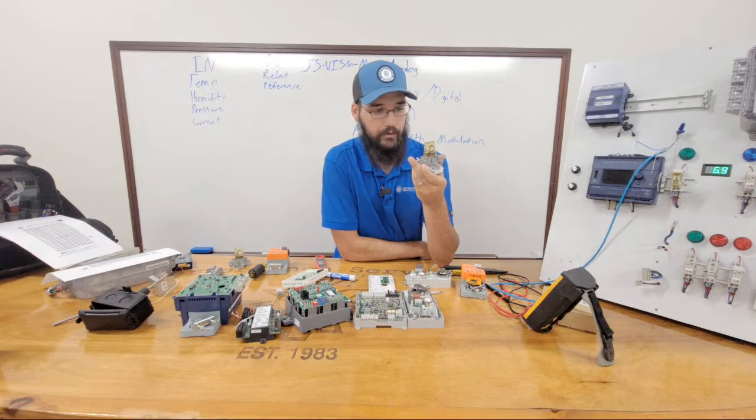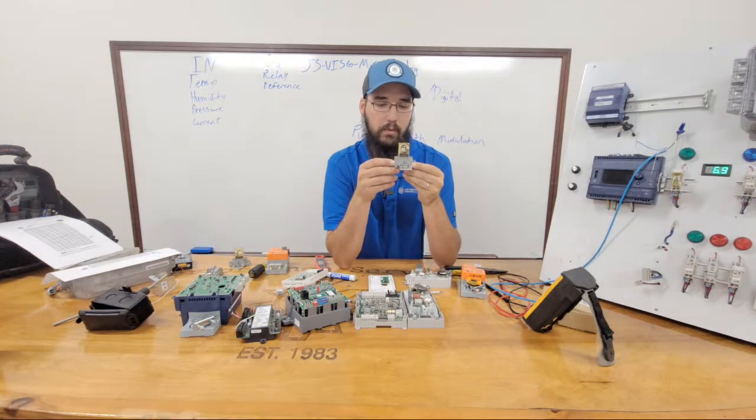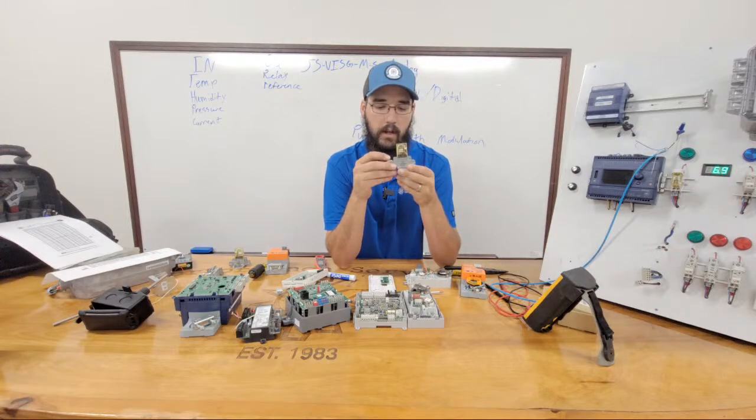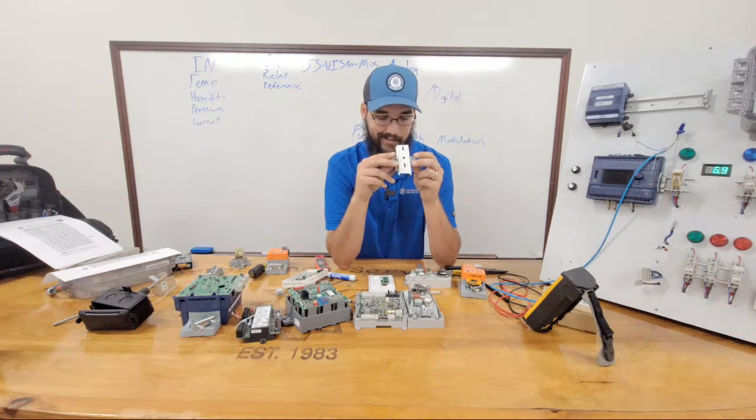Word of caution when you're using little cube relays. This particular one is a single pole double throw. So we have input on terminal 9. Terminal 5 should be your normally open, which it is, and then terminal 1 is your normally closed. And then these 2 little tiny terminals, 13 and 14, sitting beside each other, that is your coil. Now these will tell you, like this particular one says that at 120 volts it can do 7.5 amps, or at 240 volts it can do 7 amps through those contacts.